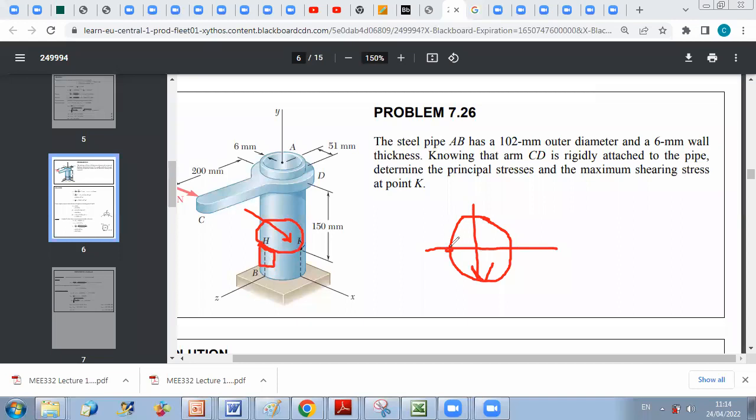It's a maximum value, because we have seen that on the neutral axis you will have maximum shear stress due to shear force, because Q will be maximum in this case. So of course, if you remember, we said Q will be maximum if the thickness is constant. If the thickness is variable, we should do an analysis to see if it's maximum or not at the neutral axis.